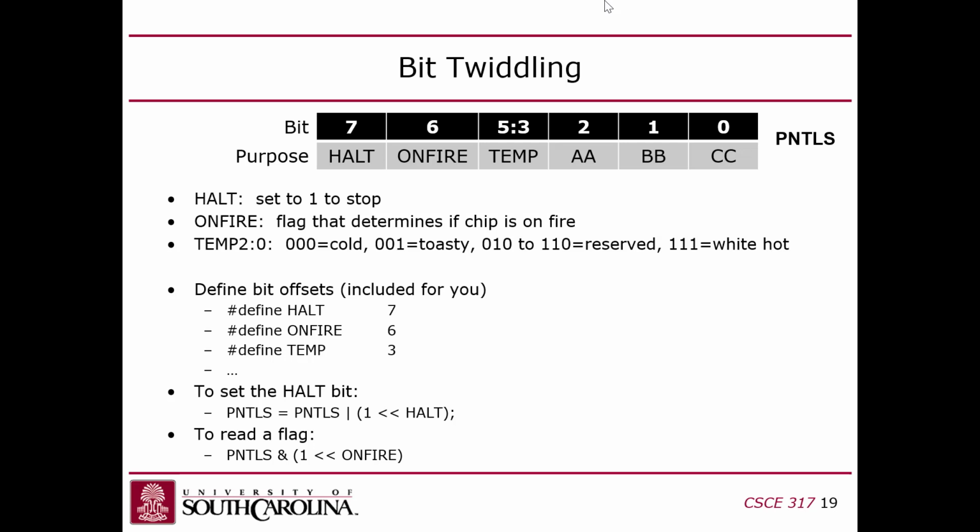So even though you're going to get a 0 or a 64 in the C language, that really corresponds to false or true, right? So if you're using that as part of an if statement or a condition, it would work. You wouldn't have to worry about fixing it up, so you would have a 0 or a 1 in there. You guys with me? Yes. But if you're going to continue using it for other bit twiddling, then you need to. Yeah, if you want to insert it into another register, you'd have to.